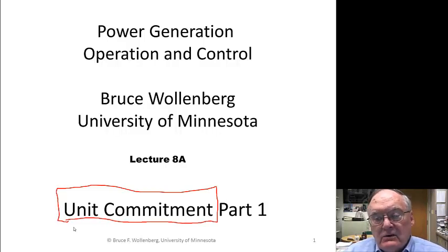And you will realize soon that we don't simply turn all the generators on and leave them on all the time until they're out of fuel or taken down for maintenance. We turn a lot of the units on for only part of the day and then turn them back off, and this is done for economic reasons. And you have to schedule enough generation to meet the load and to be safe, and we'll talk about what some of those things are. And we also don't want to put too many units on, because then we lose efficiency and it costs more.